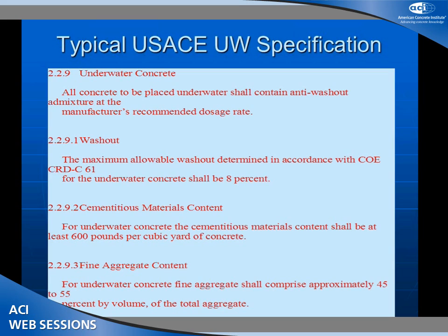Cementitious materials, everyone who has ever fooled with any type of underwater application knows the higher the cement factors, the better off you're going to be. The mix has to be sticky. There has to be some sacrificial cement. The volumes of coarse and fine aggregate, they found that it flows better as you get closer to 50-50 blends and even beyond.